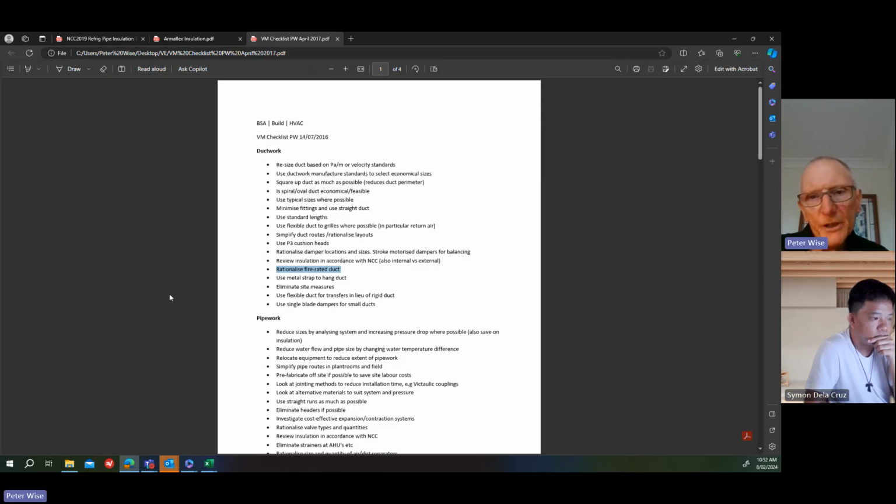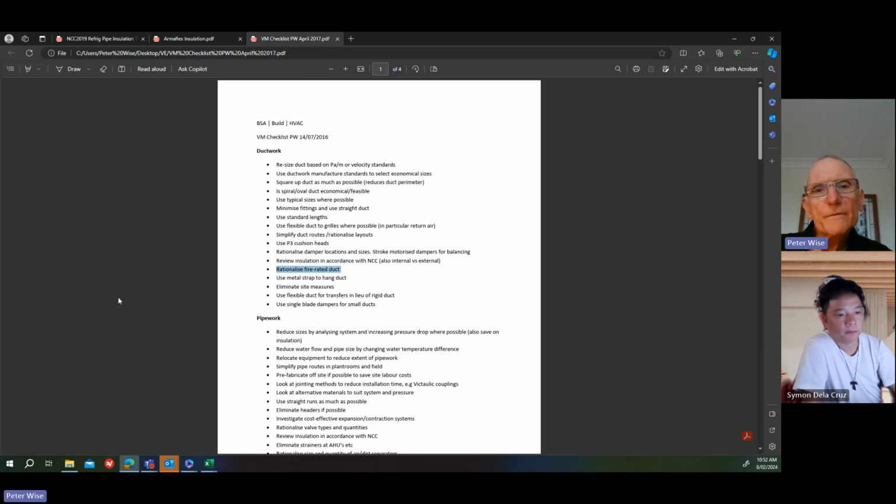So the same thing applies with kitchen exhaust. So you're coming out of a kitchen. Quite often a kitchen is a fire compartment. So as soon as you leave the kitchen, the duct has to be fire rated, because the kitchen is probably the main source of fire in most buildings. If you have a kitchen area, that's where the fire is going to start normally, unless someone lights a fire. But hopefully nobody's stupid enough to do that. So kitchen exhaust is another important one.